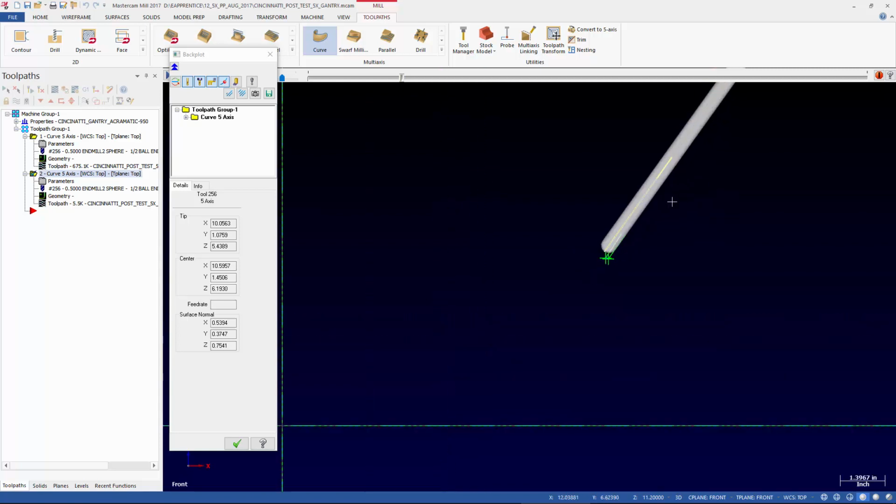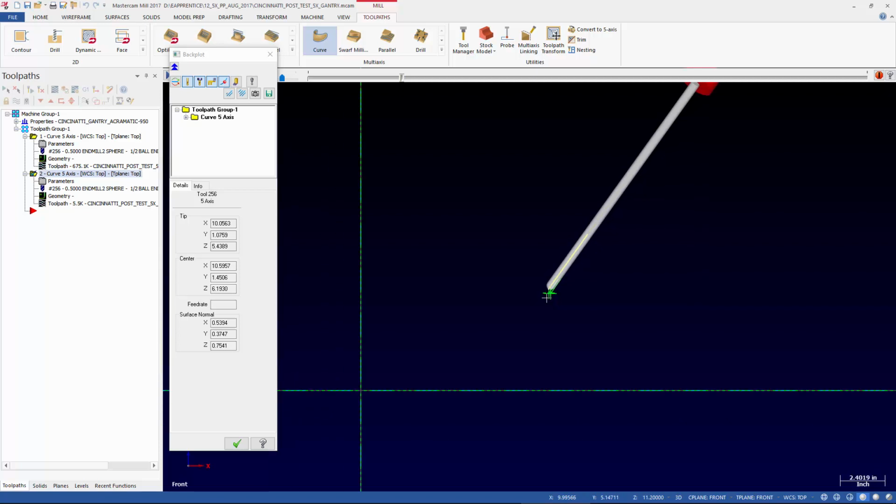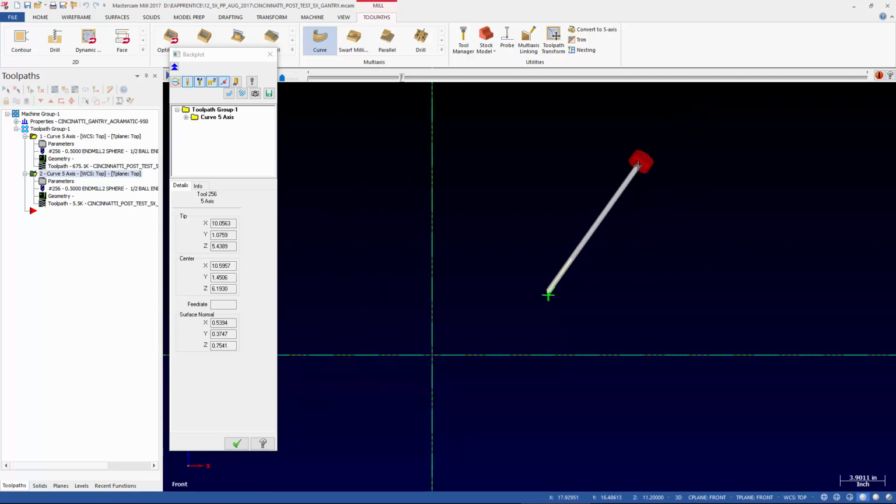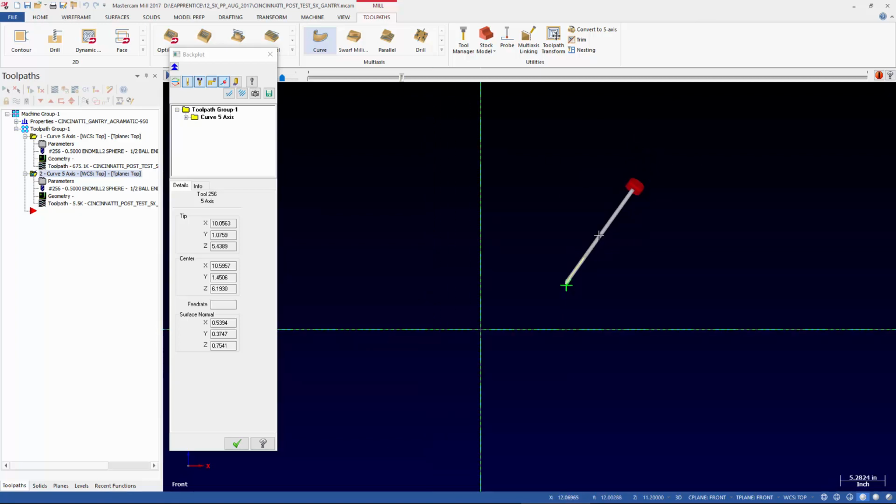So how do we go about calculating the relative position of not only the tip of our tool, but in our case, we're actually calculating the pivot point of the machine. What we don't see represented here is our actual real setup, right? We've got this tool that represents what is essentially the A-axis spindle motor, because this is going to be the pivot point of the machine. So our head is going to be located in this area right here.